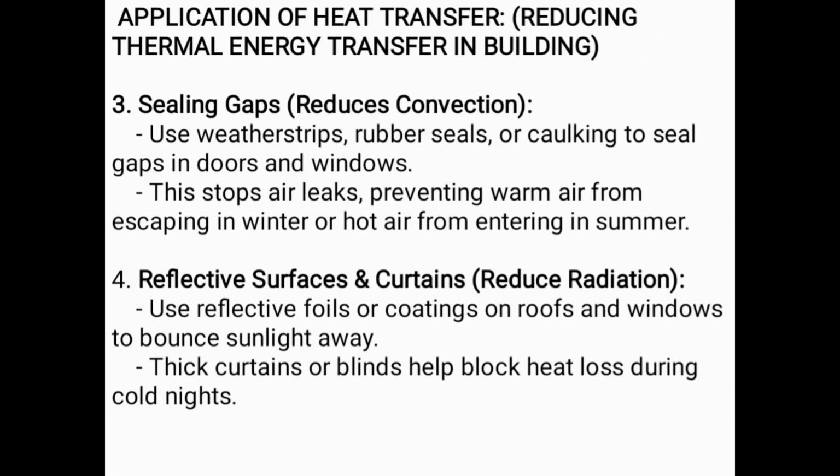3. Sealing gaps reduces convection. Use weather strips, rubber seals, or caulking to seal gaps in doors and windows. This stops air leaks, preventing warm air from escaping in winter or hot air from entering in summer.